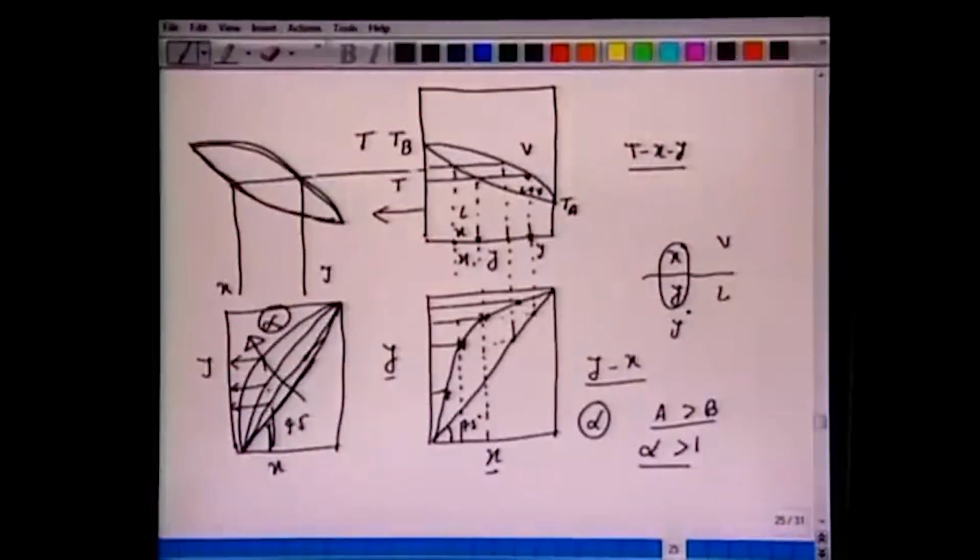These are the things which we have to understand both physically and mathematically. We can write down all these Raoult's law equations. We can also write down the relative volatility expression alpha to convince ourselves of the shape of the Txy diagram. The wider it is, the more separation, meaning Y is much larger than X. And with very small relative volatility, these curves coincide or come closer, and we have very little separation. You can write down these equations for Raoult's law and do this kind of exercise. I leave this as an exercise; you must try to convince yourself.